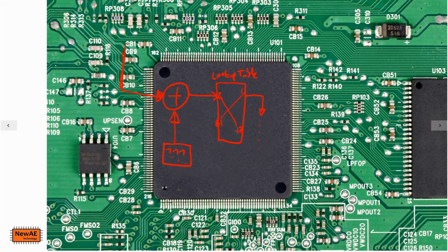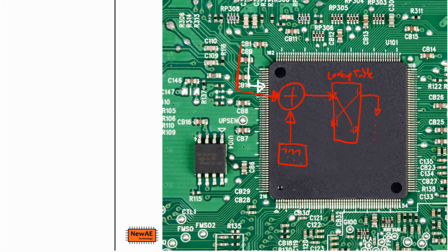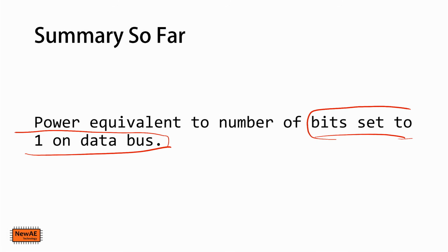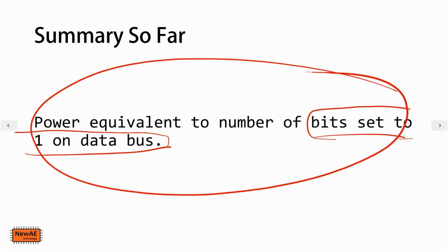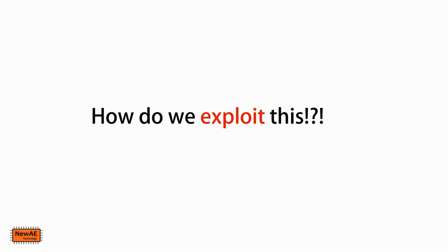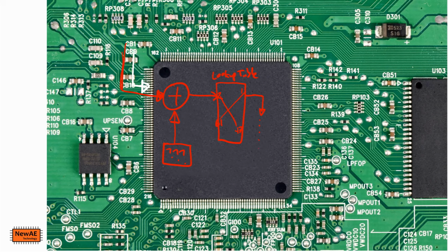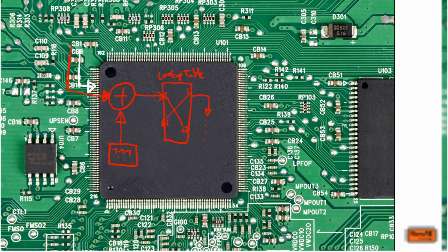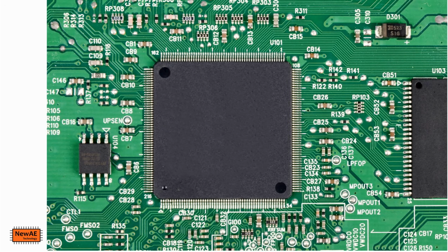So we'll send data to the device, and we're going to measure the power it consumes when it's processing. We want to exploit this piece of information here. So we need to know the power used by the device in a very precise manner. We know how the device kind of works. We can send it data, so we roughly know when it's doing encryption and decryption, but we can fine-tune that further with the attack. Now, how do you figure out what the power usage was?